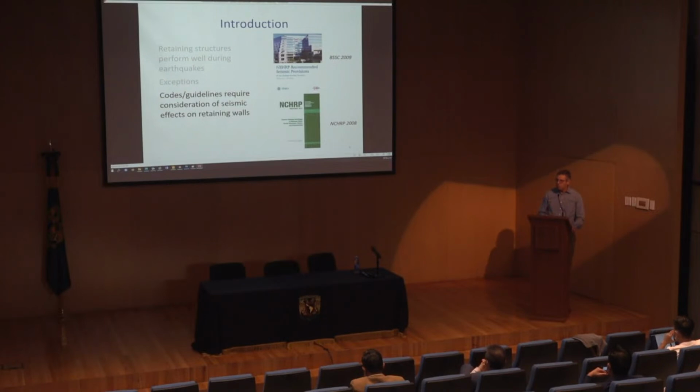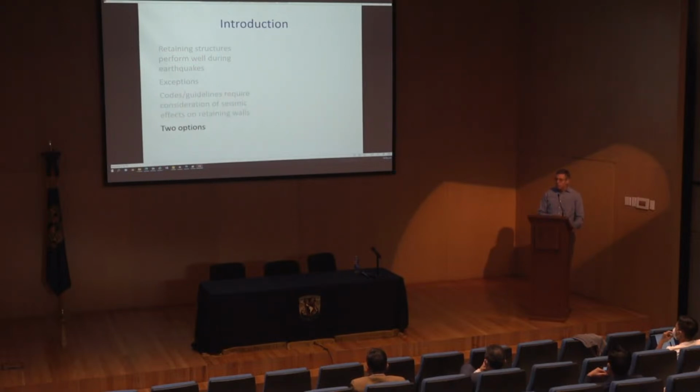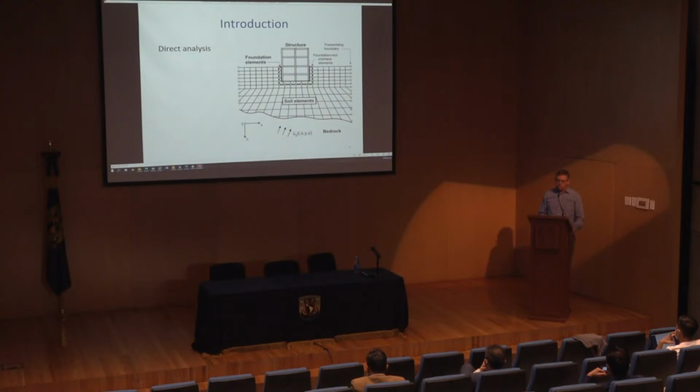Notice that the NEHRP provisions document I'm citing here is from 2009. So that is in reference to a previous version of the seismic earth pressure guidelines. There's some newer ones published in 2020. So with these guidelines documents for seismic earth pressures, there's basically two ways that are mentioned that you can do it. The first way is you can do a very thorough, we call this a direct analysis